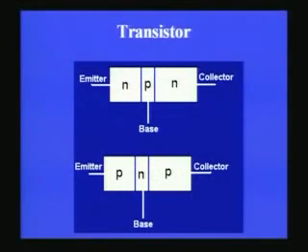And therefore you can see that there is a correspondence between a vacuum tube triode, which has 3 terminals, and a transistor which is equivalent in performance in terms of amplification action and all that, and it also has 3 terminals, and they are called emitter, base, collector. Just as the filament heats up and then emits electrons, here the emitter emits electrons or holes into the base region, and the base region is the region where the flow of electrons is controlled, and therefore it is like the control grid of a vacuum tube triode.